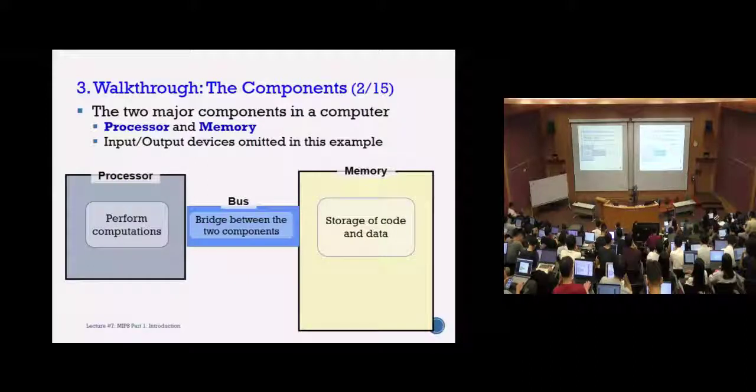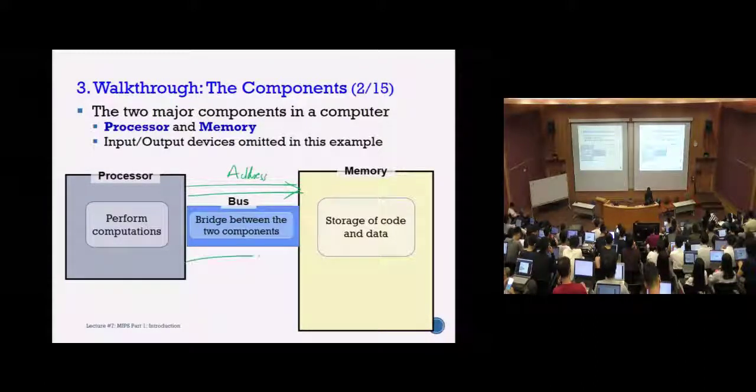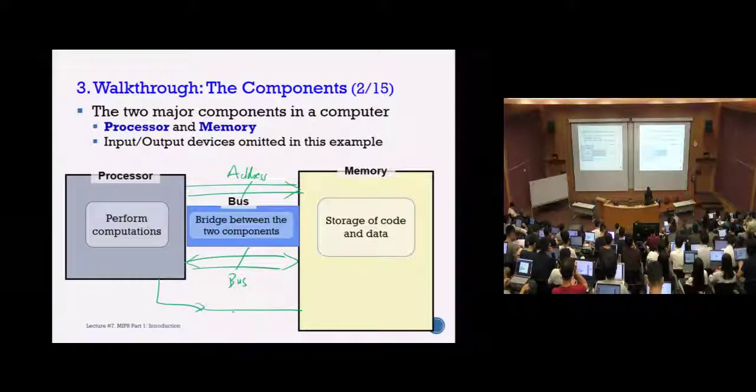At the hardware level, you have your processor, in this case the MIPS processor, and you have memory. And the connection between your processor and all your devices is what? All your electrical or electronic wiring, correct? So in essence, you have 2 buses. One is called your address bus, and the other is called data bus. Effectively, you have 2 main buses plus additional control lines that will link up your processor to your memory and so on.